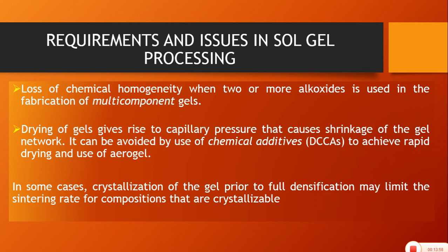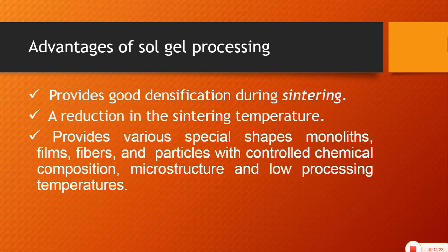The dry gel, called the aerogel, is therefore fragile and may shrink considerably during firing. In some cases, crystallization of the gel prior to full densification may limit the sintering rate for compositions that are crystallizable. So this was all about sol gel processing. Let's see its various advantages.